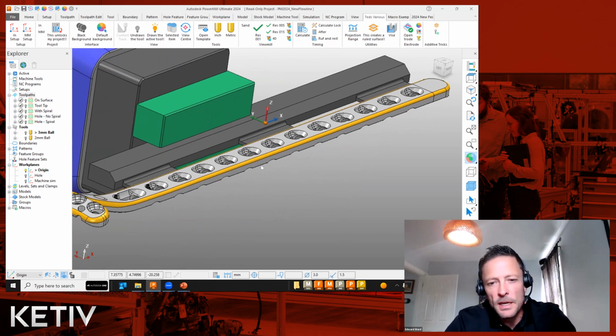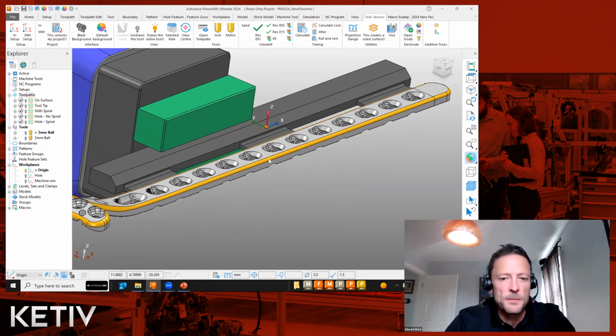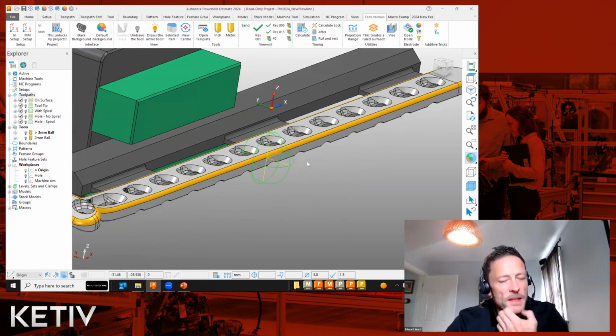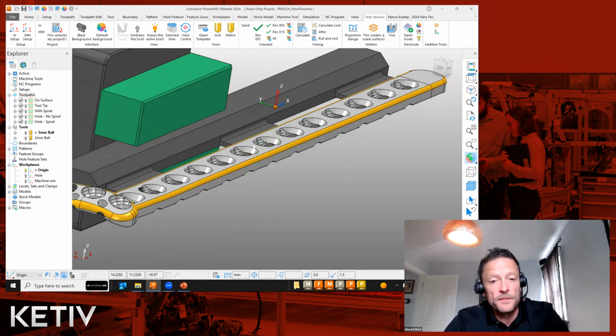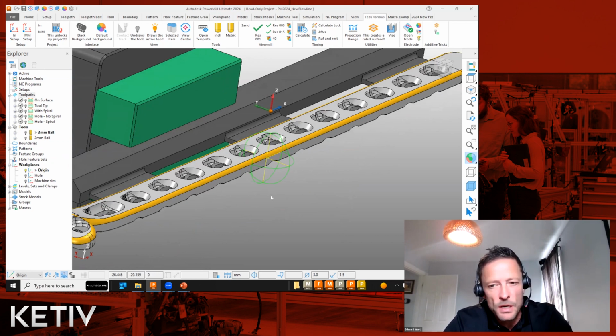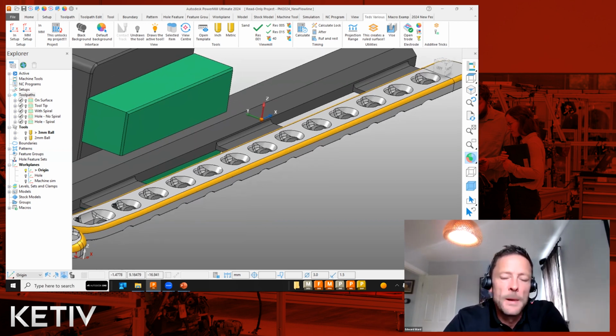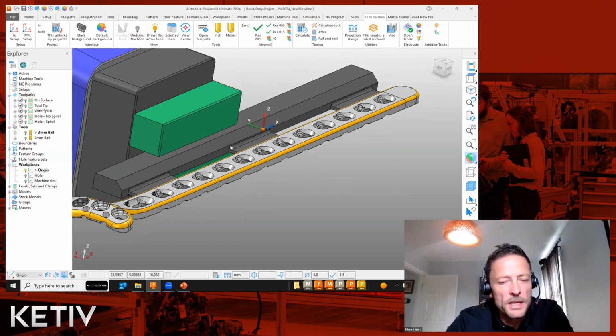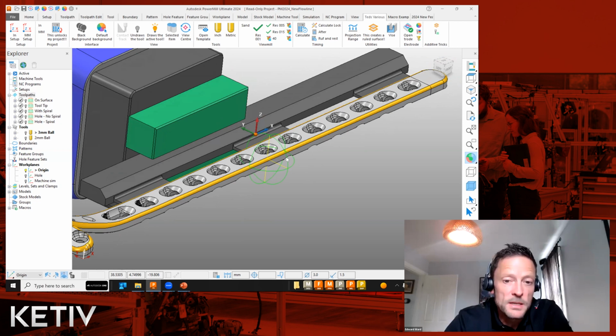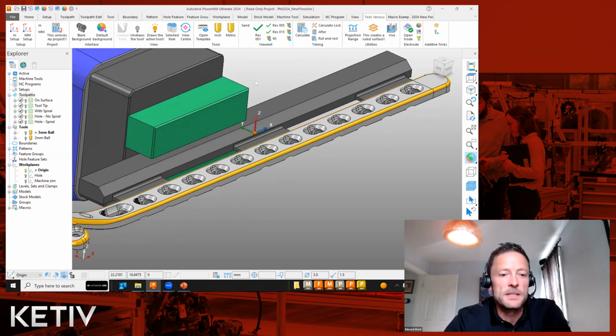Normally you would use some kind of steep finishing toolpath, some kind of shallow finishing toolpath, and then the fillets are always, what I've done in the past, the last bit to blend. Now we could do some kind of corner finishing, but that's really for internal corners, not external. So for this kind of toolpath, we've had that Flowline toolpath in the past,